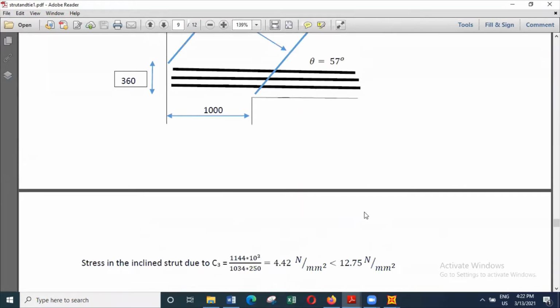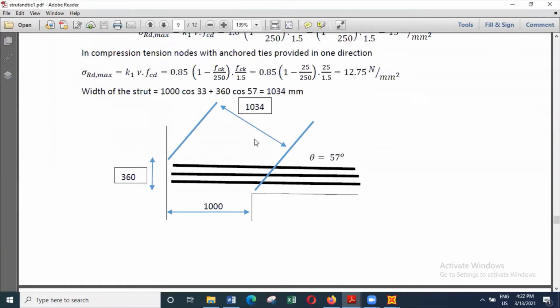And then there's another issue. Here now the loads are coming at an angle. Here the loads are coming vertically. All those loads are meeting at a place like this. So sometimes you might consider continuing the support reinforcement within the wall to a height of, say, 1 meter. So that will ensure that whatever the effect of the stress concentration can be sorted out.